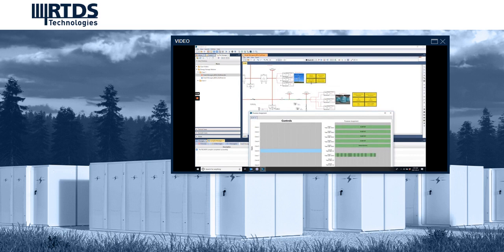The DERs and the renewables are solved in the small time step sub-step simulation environment of the RTDS, and this requires its own processor core on the Nova Core unit. Hence, fully switched power converter models are heavily resource dependent, as shown by the processor assignment. The control system components in the microgrid are solved on one core, and the power system components as well as the network solution for the microgrid voltages and currents are solved on their own core.